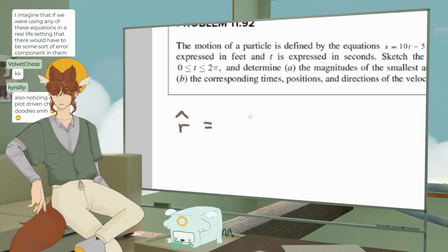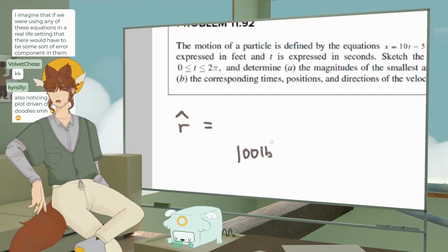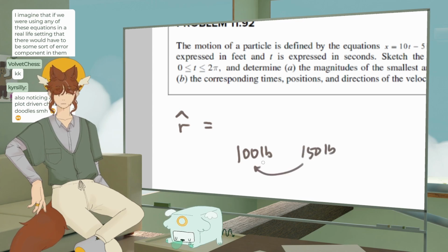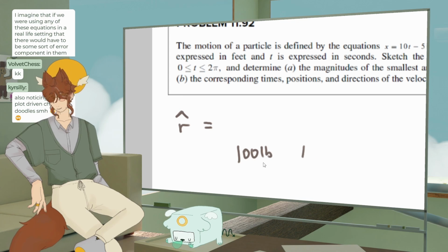there are different ways that you can counteract that error as a designer by using safety factors. But sometimes with models, we don't know what the real model is, so we can't necessarily know exactly how far we are away from it, right? So that's why we do something like a safety factor. Let's say we have a load limit and we calculated it to be like 100 pounds or something. Well, we're gonna really build it for like 150 pounds and say that the limit is 100 pounds so that we're not killing people or whatever.